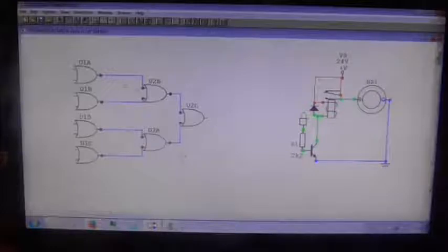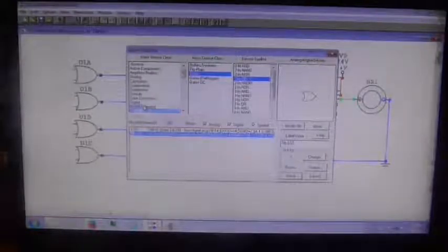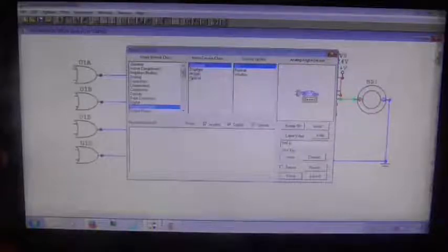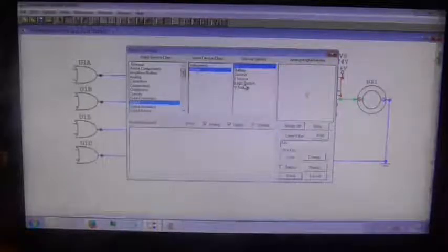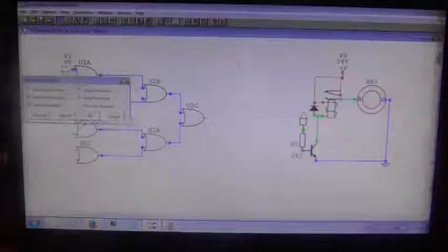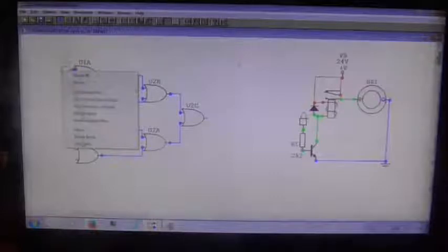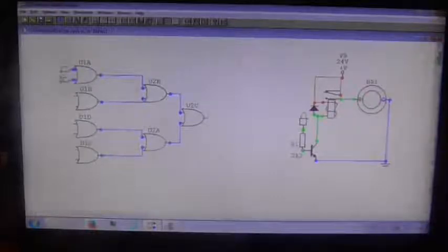Now there we are, all wired together, and now I need a logic switch to provide high or low inputs. So in digital animated, in digital I go to power and I choose a logic switch and place it in there. And again what I'm going to do is I'm going to hide the data. I don't really need it, and as that is selected I'm going to duplicate, and then I'm going to select both, and in the edit menu I'm going to duplicate, and I'm just going to go down like that,